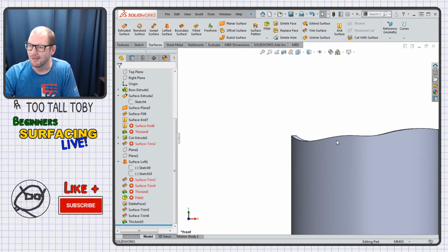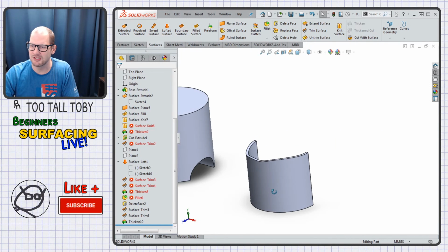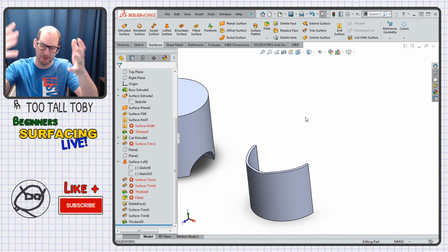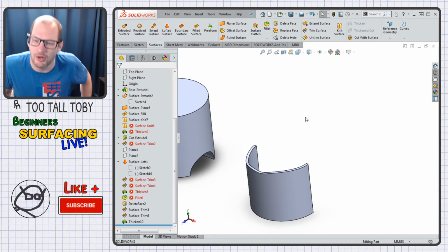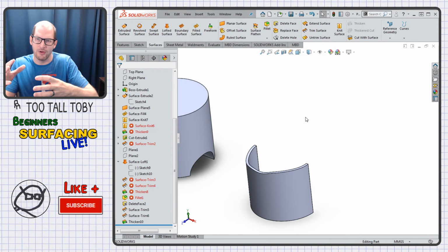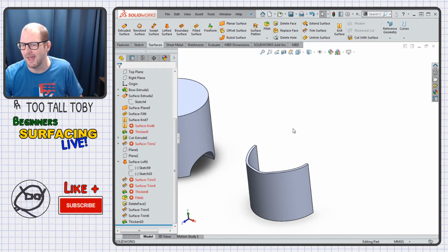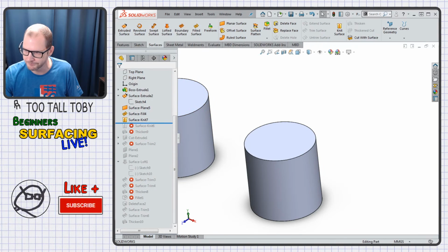but that extra edge is more realistic in the manufacturing world. So there's a lot of benefit to just drawing one surface and then thickening it to give yourself the final product. Just draw that one single surface. You don't have to worry about, okay, is this cut also perpendicular? Is this loft also perpendicular? You don't have to worry about any of that now. You just make your one surface and then thicken that one surface into a solid at the end.